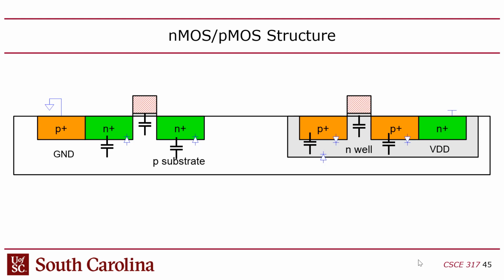Meanwhile, the transistor, when it's on, also has an effective resistance. In linear mode, it acts like a resistor, right? And it's always in linear mode, by the way, except when it's transitioning, going from 1 to 0 or 0 to 1; then it's in saturation mode right in the middle. Because as you switch a gate, you're temporarily shorting out: for a while, both the pull up and the pull down network are on at the same time, and you'll end up in saturation mode briefly. But after you settle, you're in linear mode, in which case the transistor becomes a resistor, basically.